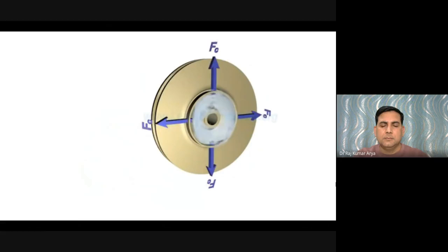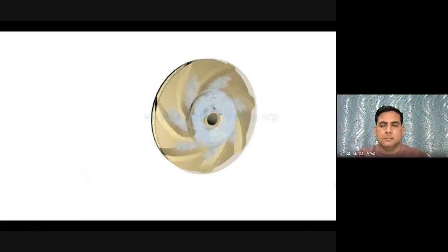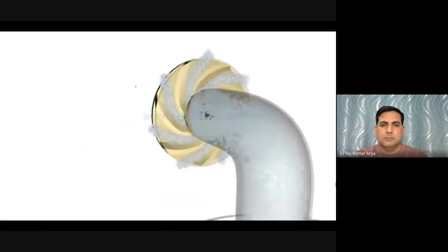Since rotational mechanical energy is transferred to the fluid, at the discharge side of the impeller, both pressure and kinetic energy of water will rise. At the suction side, water is getting displaced, so a negative pressure will be induced at the eye. Such low pressure helps in sucking a fresh water stream into the system again, and this process continues.